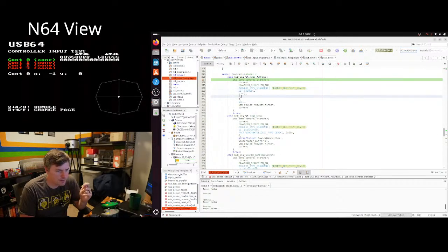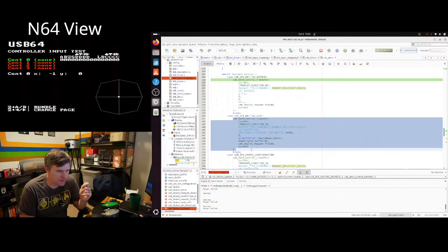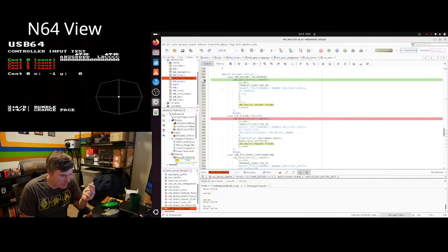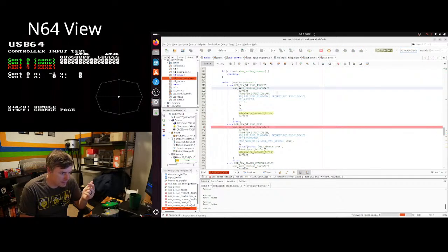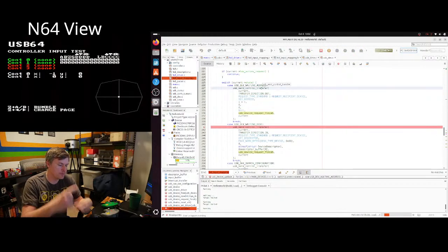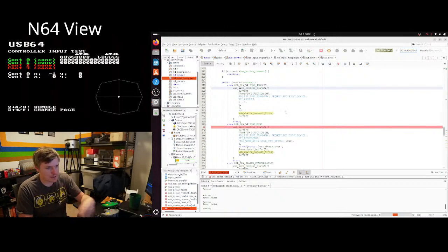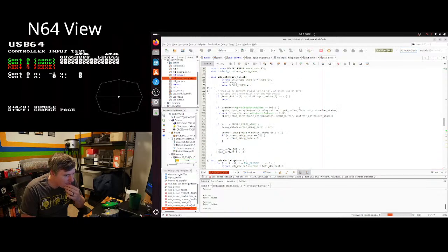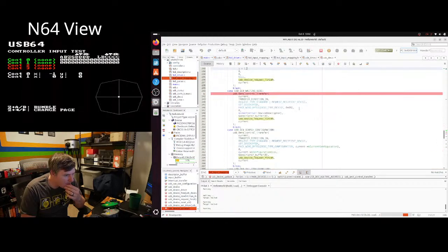I think Windows drivers actually ask it to describe itself before it does that. I don't think the order matters, but I don't expect this to be the problem, so I'm going to put a breakpoint in the next step and hit continue. So actually, this is it: every time there's a loop that's constantly checking USB, and every time it checks once. Oh, did it fail to set the address? Because I didn't hit the next bit, which I expect to hit.